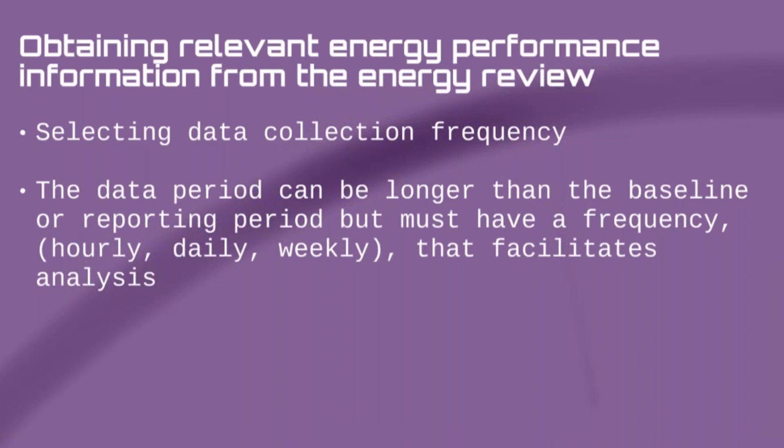If you are monitoring, sticking with the same examples as before, if you're monitoring heating in a building, taking a reading once a day of the energy used to heat the building wouldn't show up the fact that the heating was on when the building was empty. You'd need to be monitoring hourly to do that. So that's an example of why you need to be careful with your frequency selection.